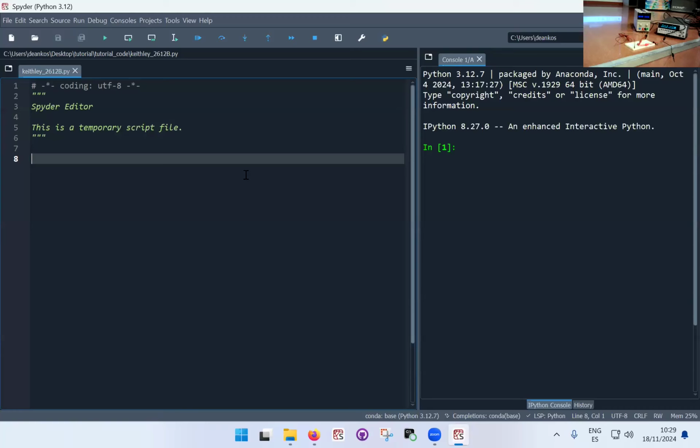Okay. So we are going to interact with the instrument through a package called pyvisa, Python VISA. It's a VISA implementation for Python. So first of all, I need to import the package. So I'm going to import pyvisa. There we go. First, if I want to check if the package is actually available, I can type it in here: import visa.